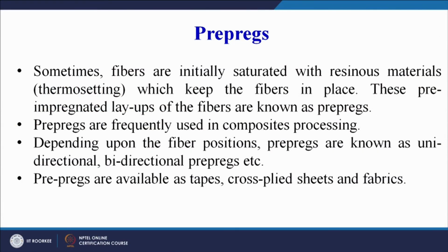We will try to achieve this target by understanding the basic concepts of prepreg, or the process of prepregging. Now, what are prepregs? Sometimes fibers are initially saturated with resinous materials, specifically thermosetting polymers, which keep the fibers in place. These pre-impregnated layups of fibers are known as prepregs. I have already explained that we have resin and we have fibers, we combine them together, and the pre-blended fiber-resin mixture is called a prepreg.